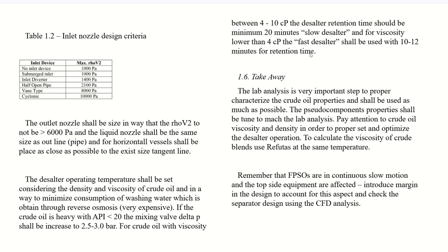What are the key takeaways? Lab analysis is a very important step for proper characterization of the crude oil properties and shall be used as much as possible. The pseudo component product shall be tuned to match the lab analysis. This is for HYSYS. Pay attention to crude oil viscosity and density in order to properly set and optimize the desalter operation, because desalters are critical for meeting the spec of the crude oil.